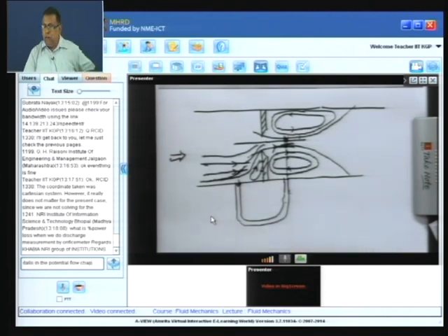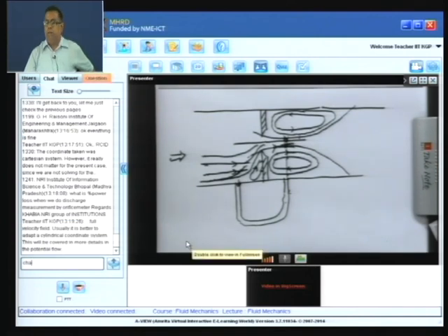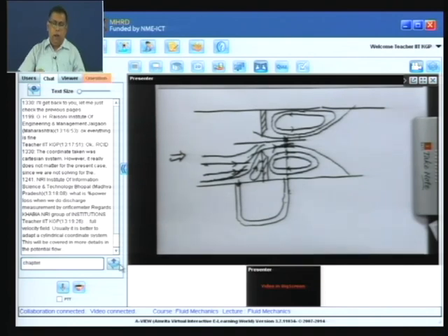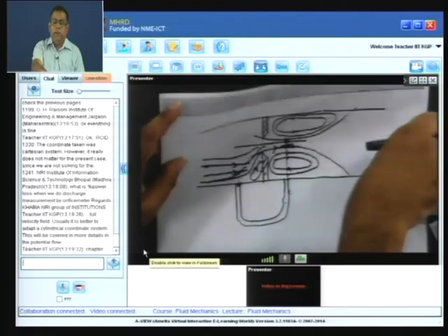So, eventually what you will find is that you will come up with an expression which is very similar to what we have obtained for the venturimeter. Now, you have to understand one thing, that we are applying Bernoulli's equation, which is only for an inviscid flow, whereas in reality you have a viscous flow. So, you can define what is called coefficient of discharge.